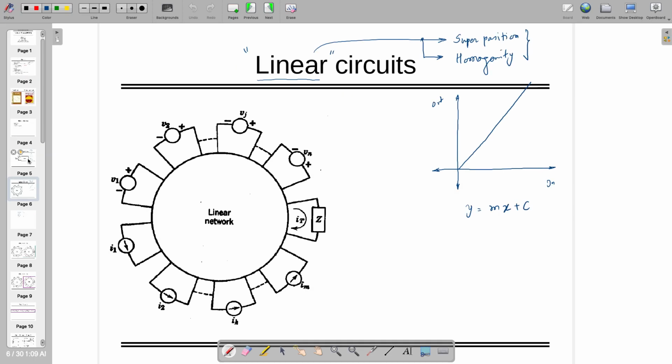So this is the title. You must have implemented superposition theorem, Norton and Thevenin. All these theorems you have applied, but there is one condition. Those are only applicable to linear circuits. They are not applicable to any non-linear circuit. If it is non-linear, the rules are different. Then you cannot follow this. You need to follow something else, maybe Taylor series, or maybe through Volterra series you can derive a different set of equations. But for linear only you can apply those theorems: superposition, Thevenin and Norton.